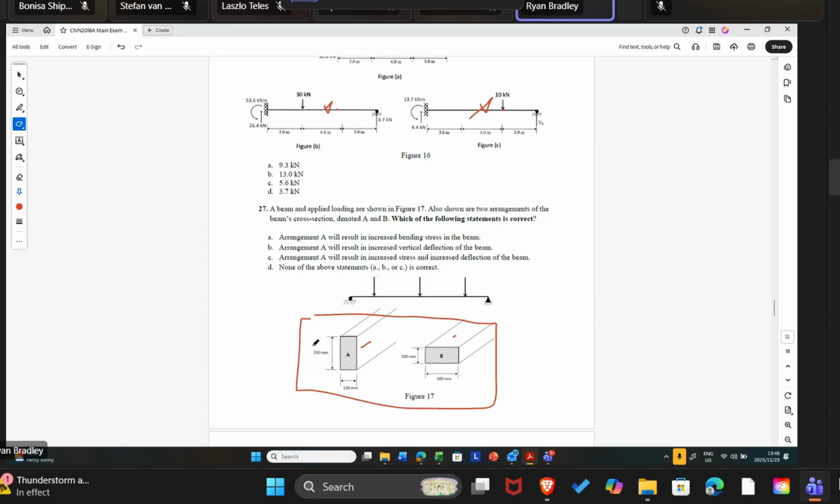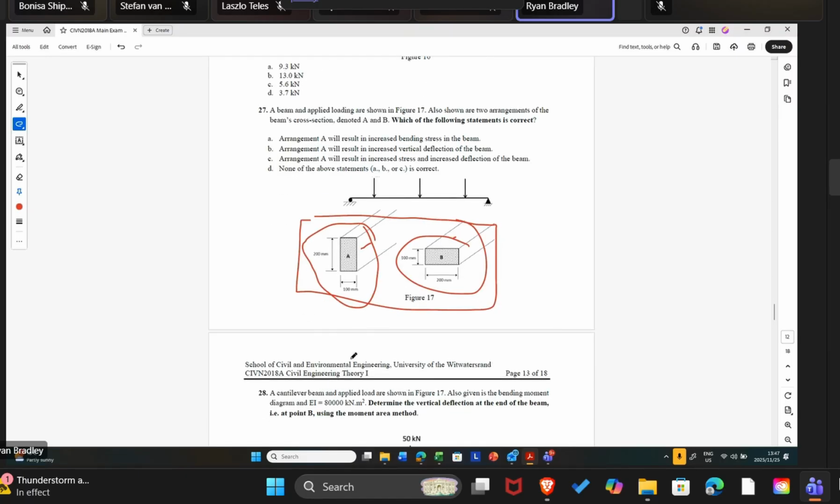Okay, so there's a reason why we position beams like this and not like this. You might see beams like this, but there's clearly an understanding that in that arrangement, it might be for space requirements. Maybe there's a clearance requirement or space requirement that we might place a beam like this. But if we had that same cross-section like this, we do get a huge advantage in terms of deflection, reduced deflection in the beam.